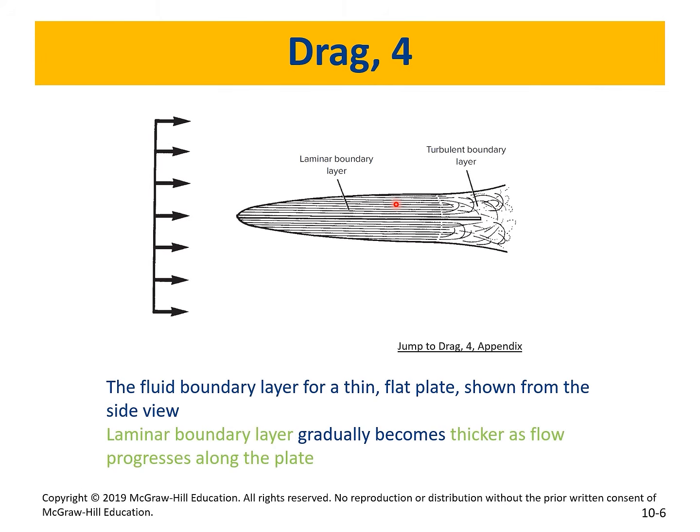Now, here's the thing. What's going to happen is that you're going to have a difference in pressure here and there, correct? So the difference in pressure is something we call form drag, because you have two different forms of the layers of the flow, right? So that's form drag. So you have viscous drag, which is resistant drag, and then you have the form drag. Does that make sense? How we look at that?